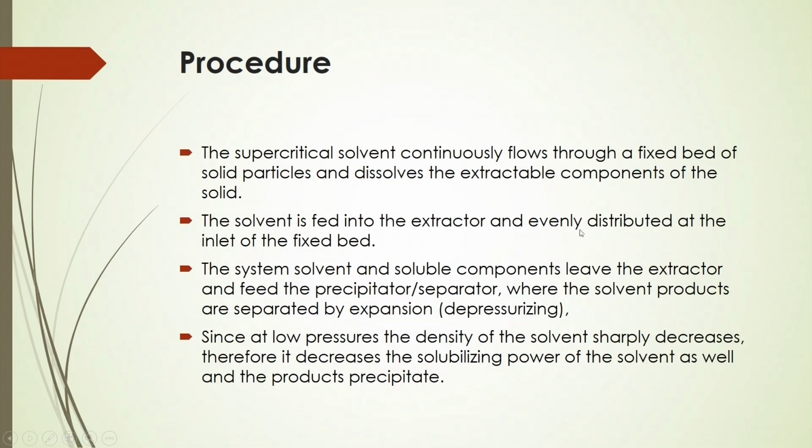Now, the supercritical solvent continuously flows through a fixed bed of solid particles and dissolves the extractable components of the solid. The solvent is fed into the extractor and evenly distributed at the inlet of the fixed bed, and the solvent and the soluble components leave the extractor and feed the precipitator or separator, where solvent and products are separated by expansion.